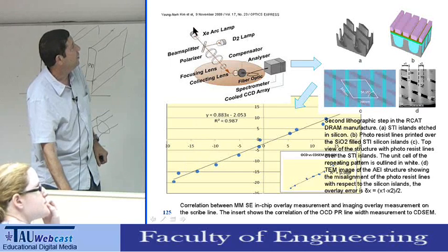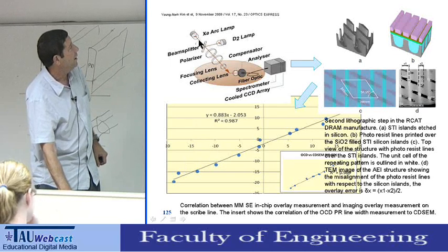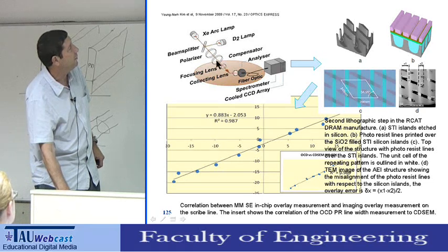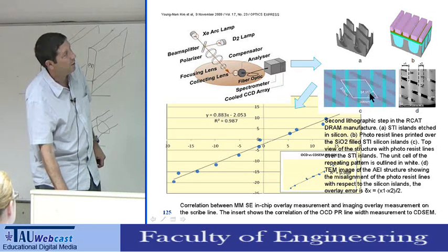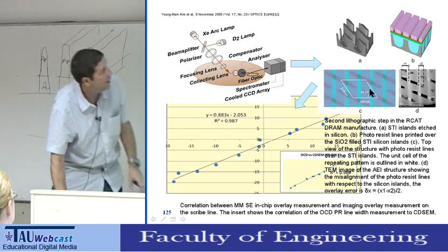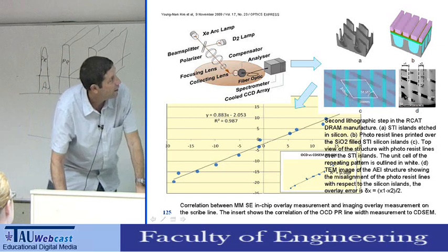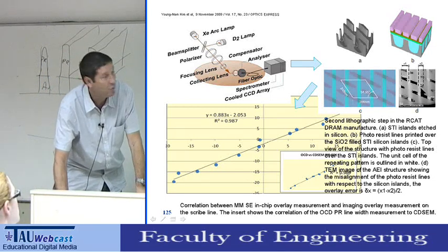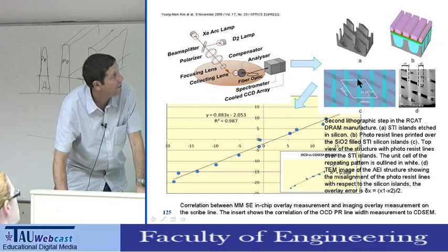And what I can actually do, for example, is illuminate it. In this specific one, this is a scattering system where I polarize the light. I illuminate my structure, and this is how it looks. This is my DRAM, this is an actual DRAM, and one is the simulated region, one is the real image, and I fit.